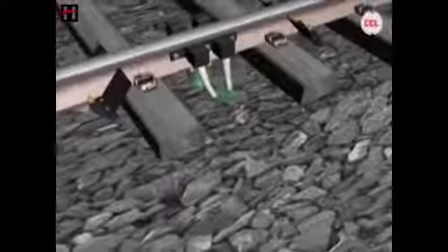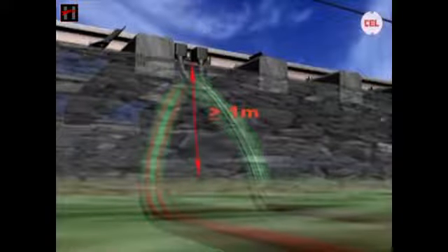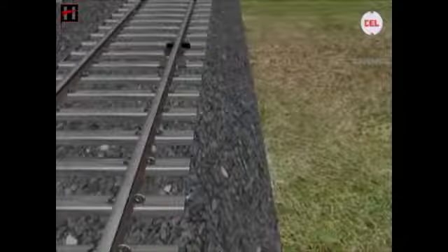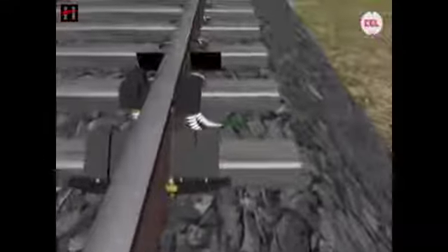9. Ensure that the HDPE pipes are laid at a depth of not less than 1 meter from the bottom of the rail. And lastly, ensure that TX coil and RX coil cables should run separately in different HDPE pipes at a minimum separation of 400 mm.